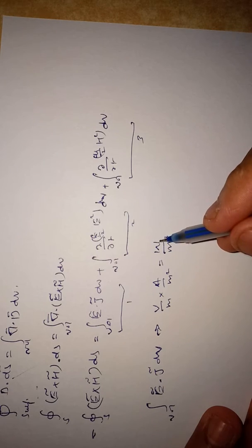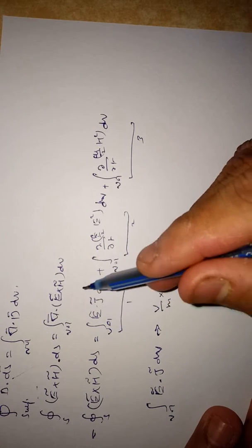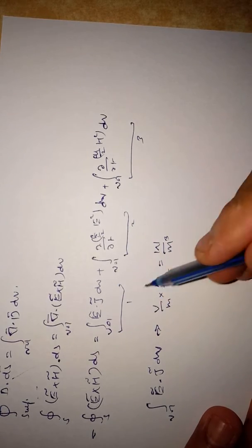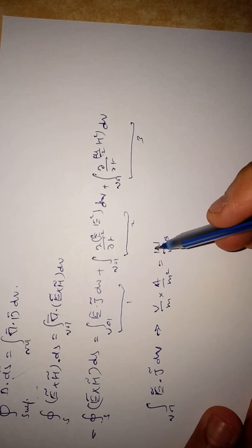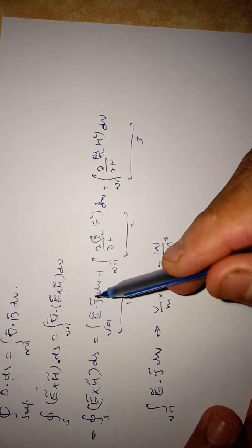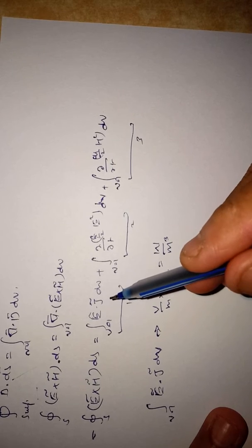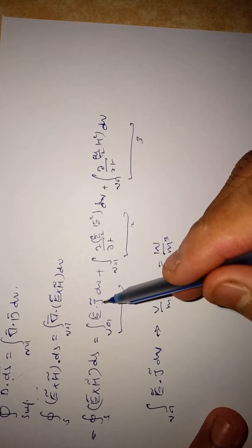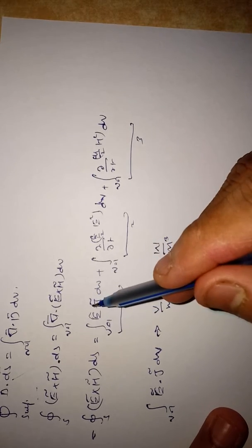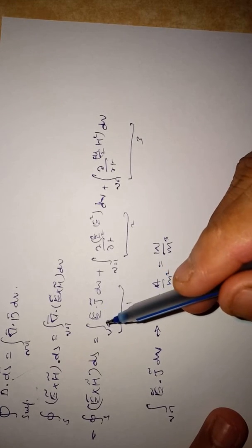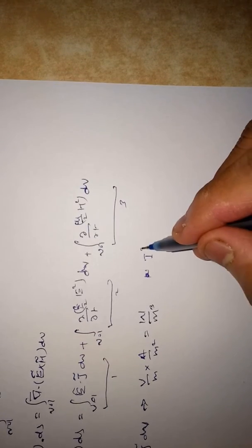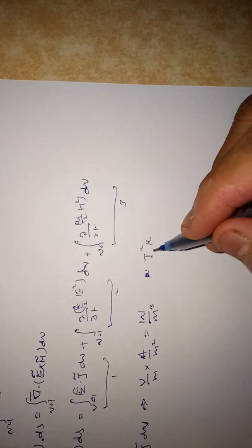So this gives instantaneous power. This term shows the instantaneous power which enters the volume, because it is a volume integration, and the unit also shows power per unit volume, meter cube being the unit of volume. It has a term J square, and J is the current density, so it explains current. This power will dissipate in terms of current loss, like I square R losses.